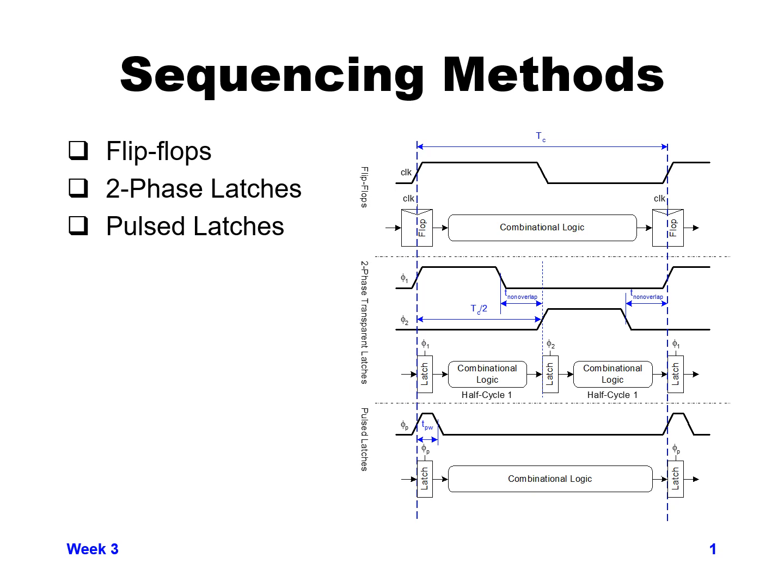And the way this works is when the phase 1 clock goes high, it will capture a value that will go through the combinational logic. The phase 1 clock goes low, so that value will stabilize before the phase 2 clock goes high. And so we make sure that the combinational logic is a short enough logic path that that value becomes stable before the phase 2 clock goes high.